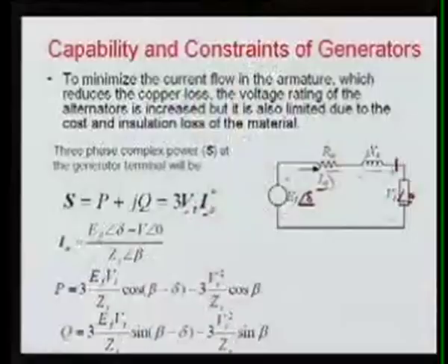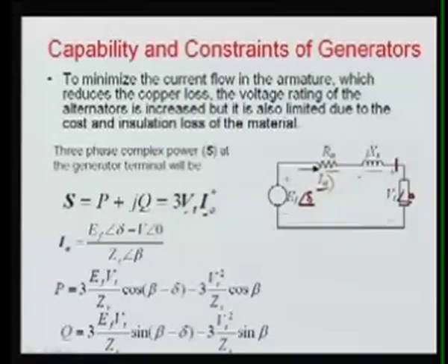So this is delta, that is with reference to this voltage 0. If you are taking here, let's suppose 15 degree of this voltage, then here this will be your delta plus 15. So this is basically, I can say, with the reference to this terminal voltage, this angle delta, that is the power angle. So we can write the current which is flowing, this voltage, that is voltage EF angle delta, minus this voltage divided by the impedance here, which I have written here.